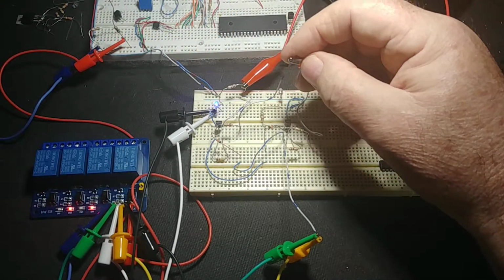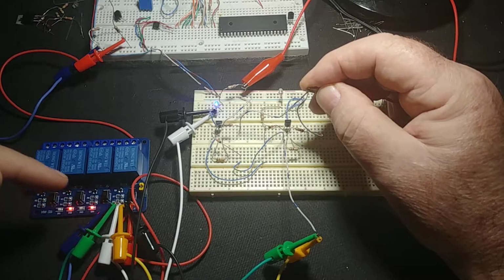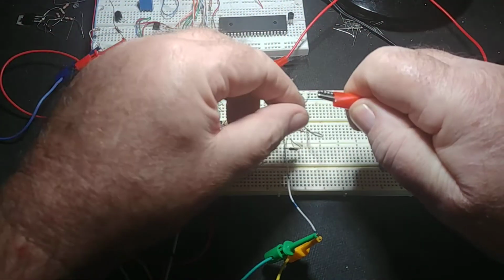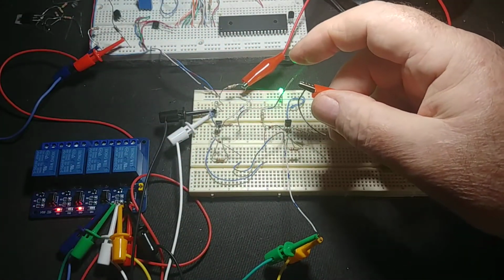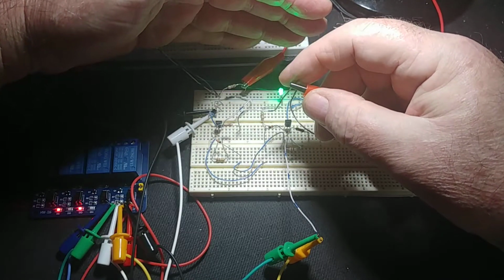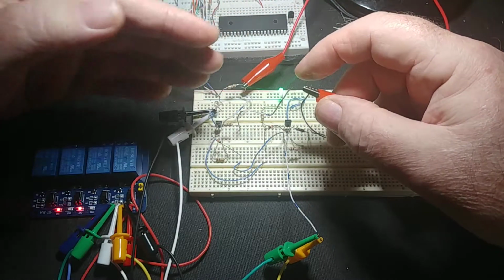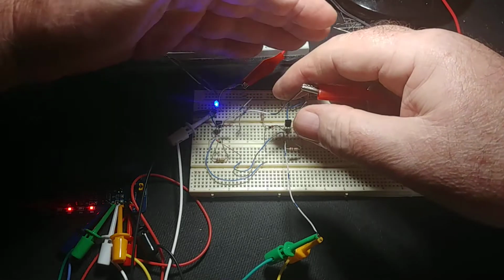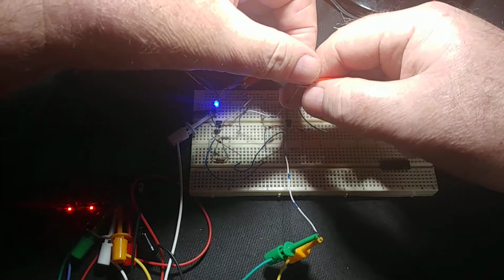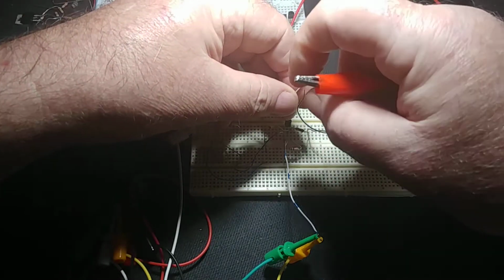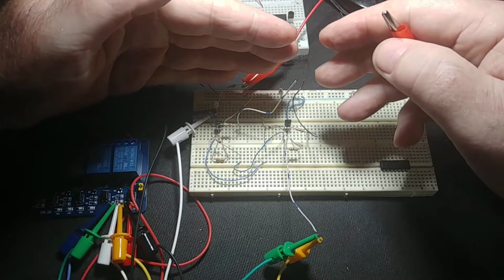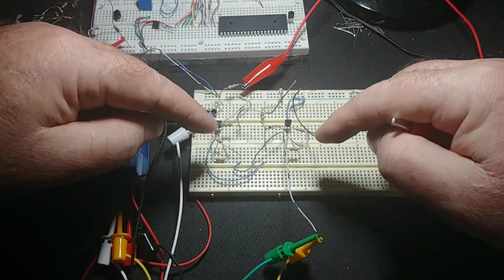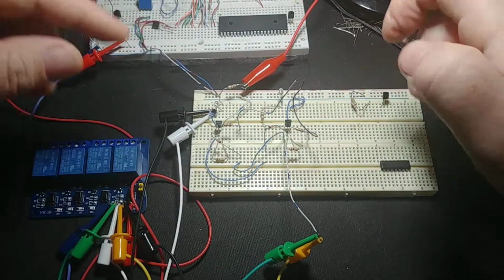And the same thing with the other side. See the blue light's on and it turns on 2 and 4. So the protection that I'm putting on this is if I short these together, nothing happens. It doesn't switch or short out the H bridge. Same thing on this side, and I short it together. Nothing happens. So what if we try, and you can see there is an off condition. So there's nothing when there's no potential on this at all because the two pull down resistors pull down the FETs and shut them off.